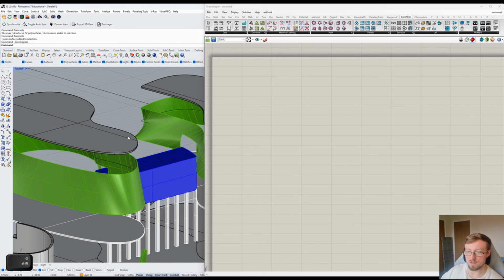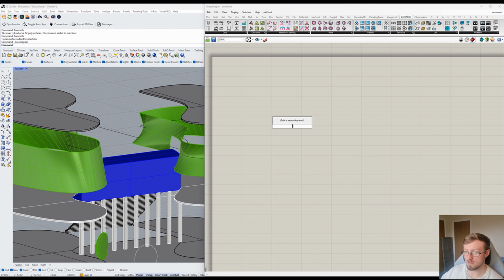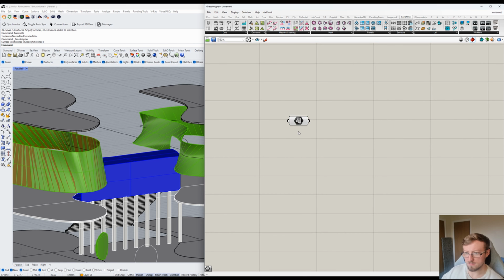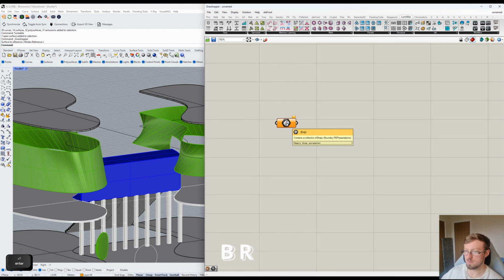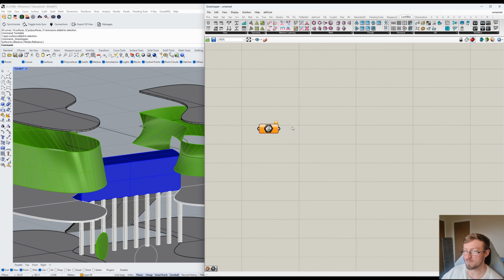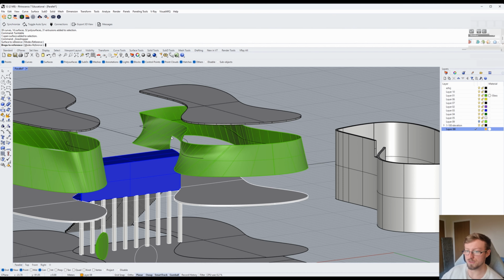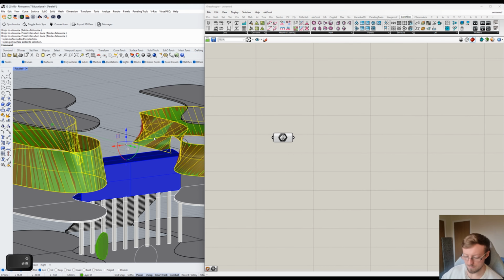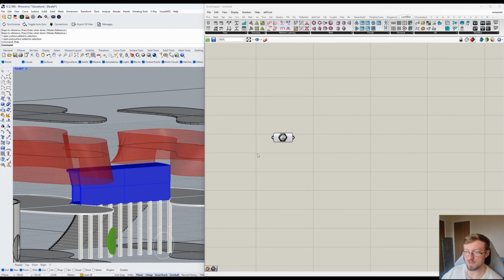So yeah, let's say we wanted to create a paneling system with these two. I'm pretty sure they aren't surfaces. If I go to click a surface, that one is, but that one isn't. So to make it easier, we're just going to create a prep, which is basically consisting of lots of different faces. What we can do is select multiple. Let's click these, and let's just hide these. So you can see that that's selected because it turns green.